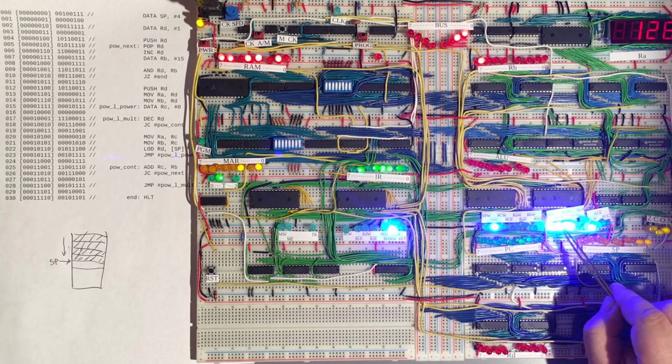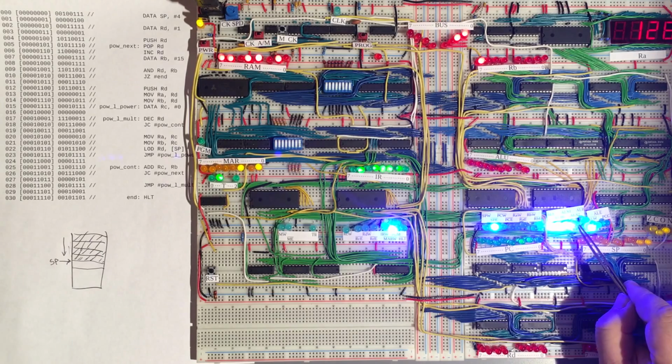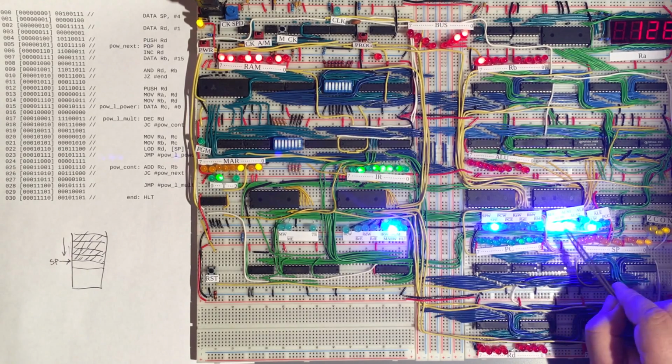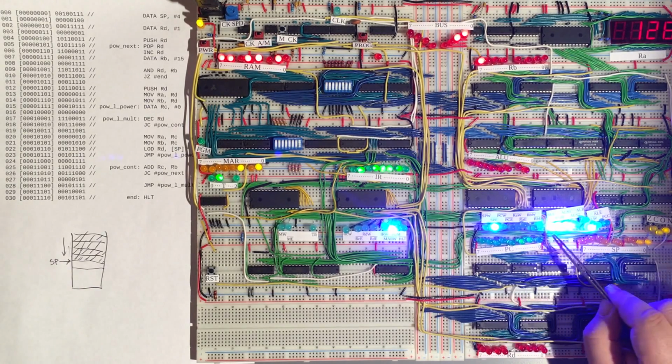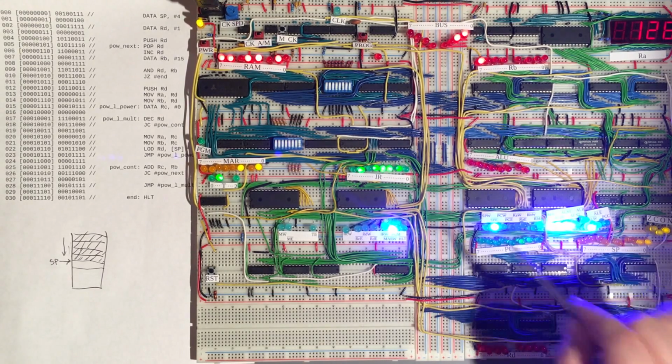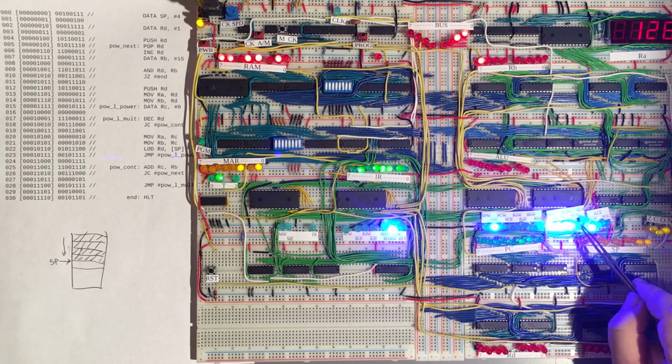And as we can see here, what the ALU will do is a 0, 1, 1 operation, which in fact is an A plus B operation. And so the first operand will be this 3, the stack pointer. It's also asserting the carry in flag on the ALU, and so it will add 1 to whatever the result of our calculation is. And the second input is not the B register, because we haven't asserted this ALU B signal. And so the second input will in fact be 0.